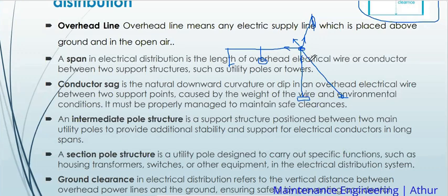A stay wire, we have different types of stays. We have this one that you always see from here up to the ground. This one is to protect this pole from being pulled inwards, because you see there is a tension here and there is a tension here. Here we put what we call a normal stay. This structure is supposed to have a normal stay, which is from up on the top of the pole to the ground.